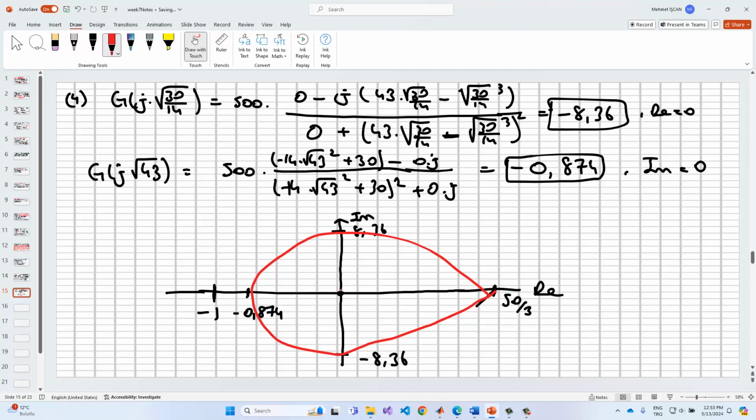And also we have the circle in here with the radius of the 500 divided by s1, s2, s3. This is coming from the open loop poles 1, 2, 3. So also we can have the one encirclement in here, just like this one, because we have the frequency values in here, and so the limits in the real part and in this part.